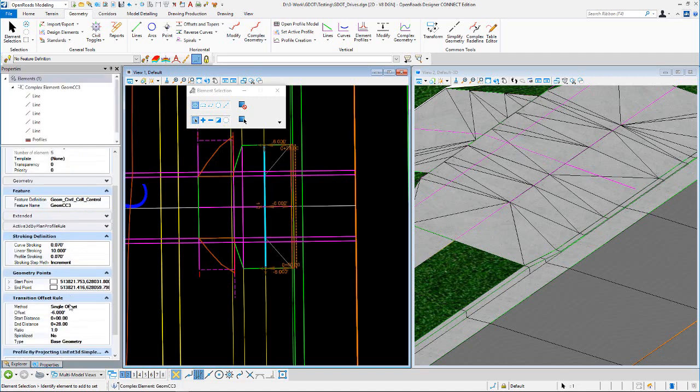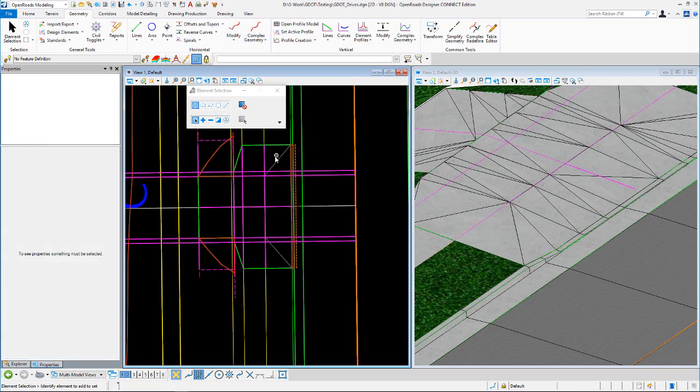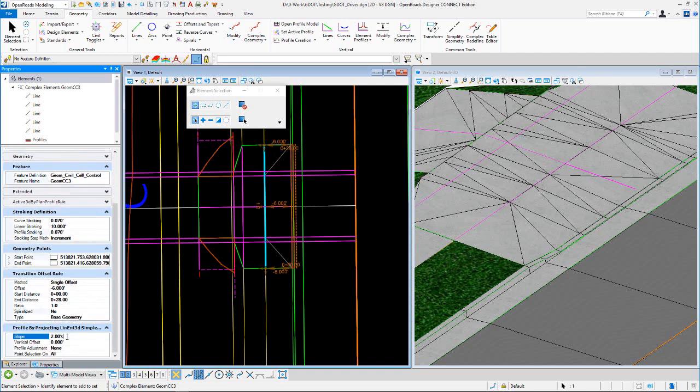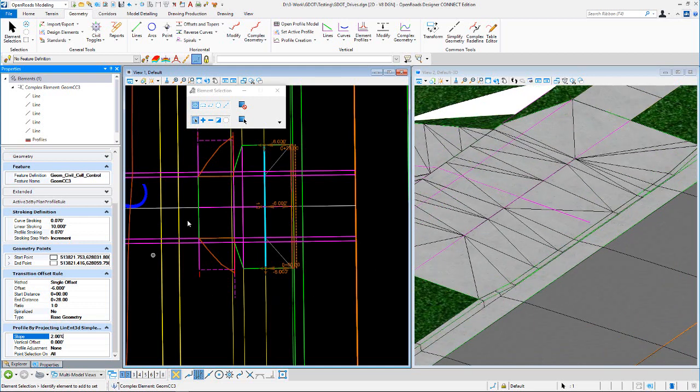But if you'll notice, go down and look at the profile here, it is positive 2%. That's actually coming off of the back top of the curve. So positive 2. So you basically come in here and control your slope there as well. And really what you need to do is just match whatever slope you've got on that buffer and that sidewalk and all that. That's all we're doing.